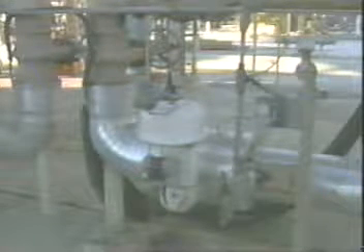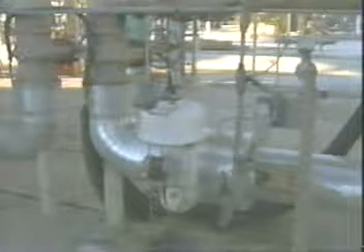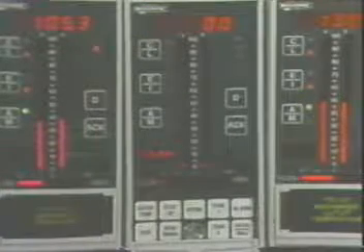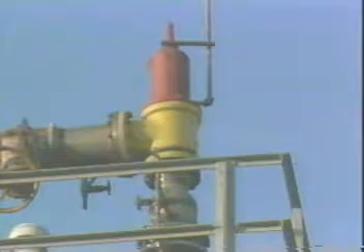When used in a continuous process such as this, the function of the control valve is to modulate the flow of the process fluid. So, for a control valve in this type of application, flow characteristics are a primary concern. You should also note that control valve position is dictated by an external controlling device, such as this digital controller. Safety relief valves and other self-contained regulators are not normally considered to be control valves.